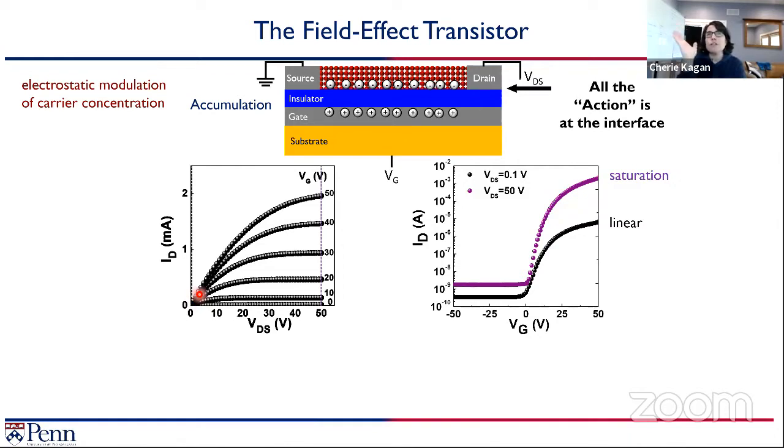And it comes back to thinking about this as a resistor, which would have linear current voltage characteristics. What happens is as you push the voltage higher on the drain, this drain bias affects the carriers locally. And at some point, it's something that's known as pinch off. I won't go into that in detail here, but then you get a saturation in how the carriers can flow through this region, and they level off and hit what's known as saturation.